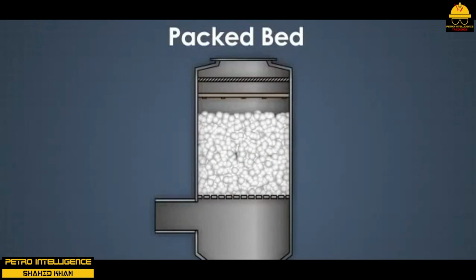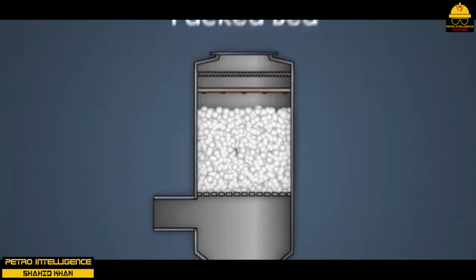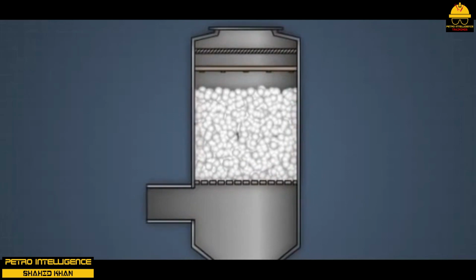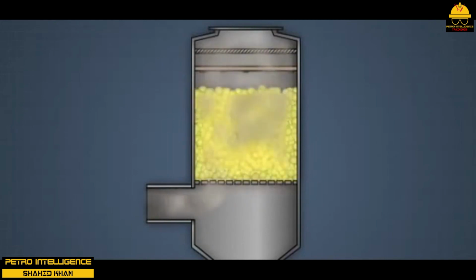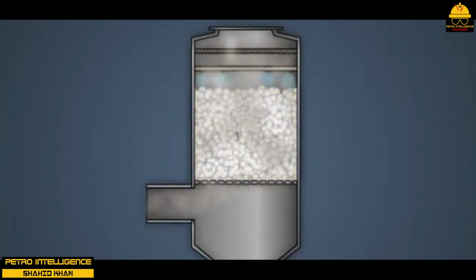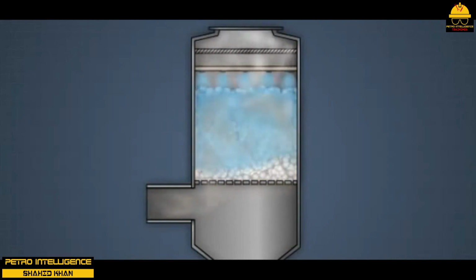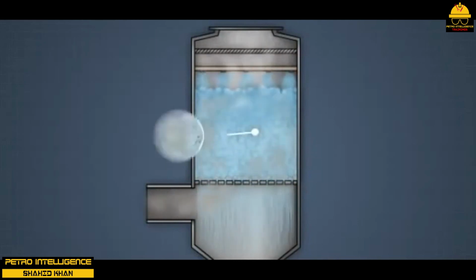Scrubber. A scrubber is a device used to remove chemicals and solids from processed gases. Scrubbers are cylindrical and can be filled with packing material or left empty. As dirty gases enter the lower section of a scrubber, they begin to rise. As these dirty vapors rise, they encounter a liquid chemical wash that is being sprayed downward. As the vapors and liquid come into contact, the undesirable products entrained in the stream are removed.